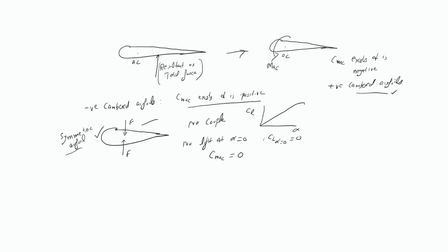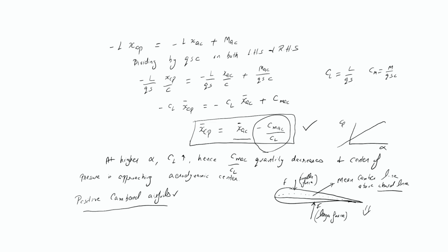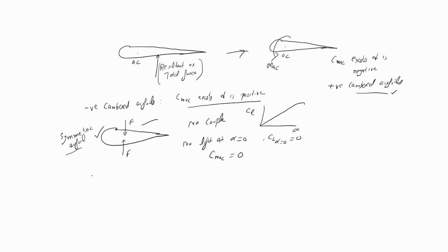Now similarly, if you see this equation, for the symmetric airfoil this equation reduces to XCP equals XAC bar, since CMAC itself is 0. Please remember this point.